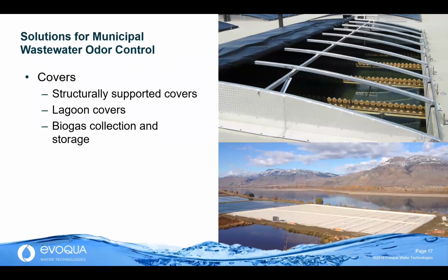You kind of get the sense when you look at the image on the bottom right, that lagoon is absolutely huge, and the cover has been custom made to go over that. And aside from being a good neighbor and covering up a bad odor, covers make sense when you're collecting biogas for energy conversion and when you want to control temperature and algae growth, and plus they reduce contamination and disinfection byproducts. Now there's also a new system of structurally supported covers that perform the same functions we just mentioned, plus they're airtight and they allow off gas to be reliably captured, and the covers can be retracted to provide easy access for inspections and maintenance.